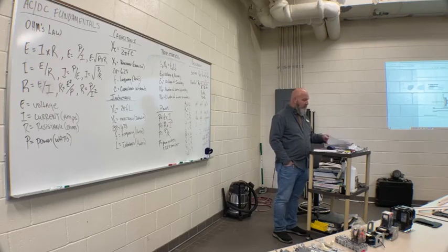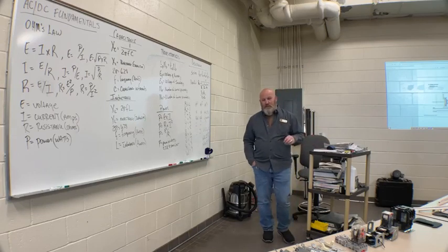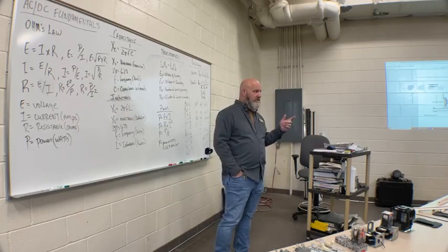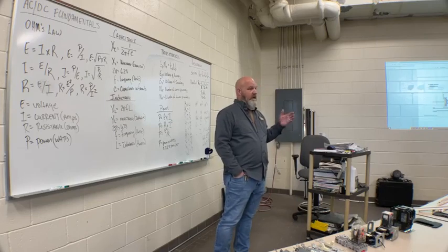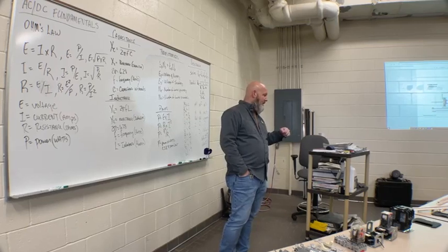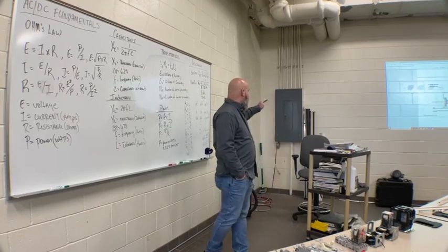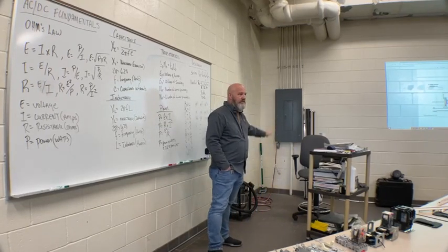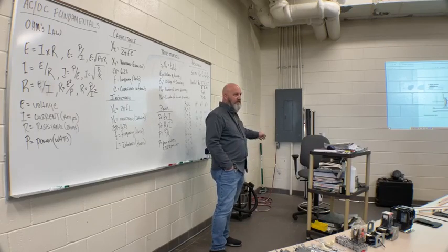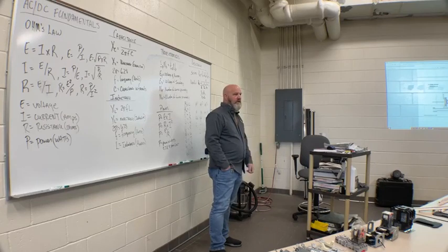For one of the examples, and students miss this one, is accessible and readily accessible. Now, to me, some people say that's the same thing. If I say an electrical panel has to be readily accessible, that just means I don't have to move anything to get to it. I don't have to go around anything, I don't have to move anything, I don't have to jump over anything.